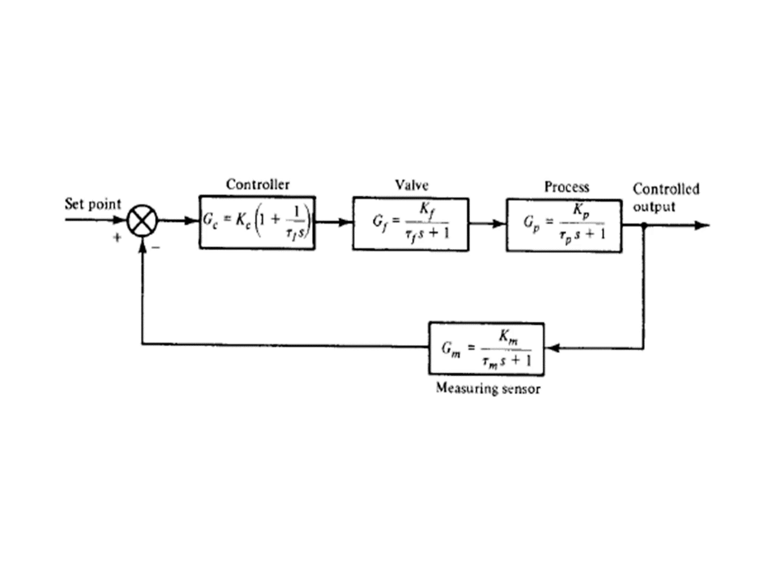In the previous case the process is well known, a mathematical model is available because we know the model, and auxiliary measurement is also possible, and by measuring the value we can schedule or program the adaptation mechanism. That is called scheduling or programming. The next one is gain; we are concentrating on gain scheduling.